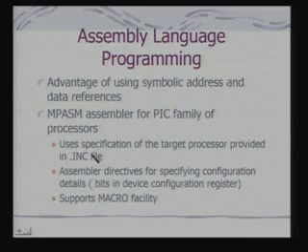In fact, if you are using an 8086 or 8085 assembler, your processor configuration is pre-specified. It is part of the assembler itself. But here you are using an assembler for a variety of processors. So you have to specify your target processor by selecting an appropriate .inc file. This is a very important exception here.